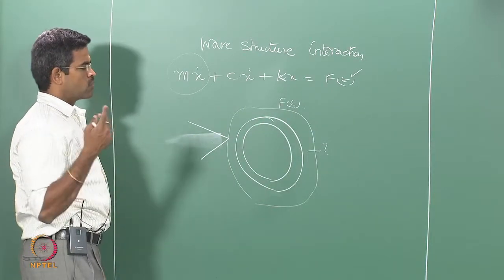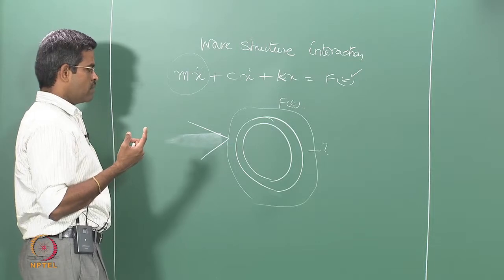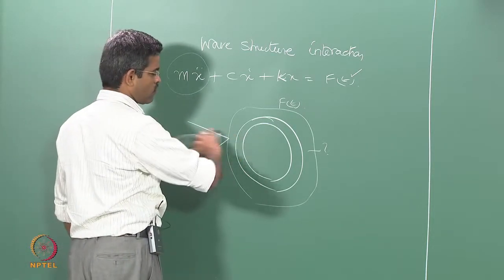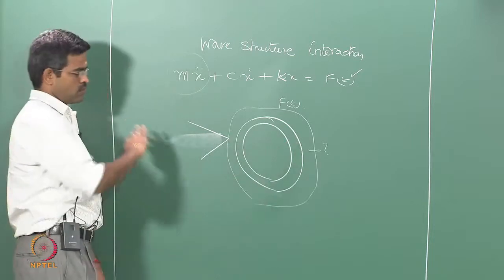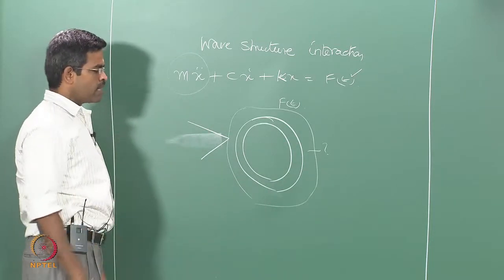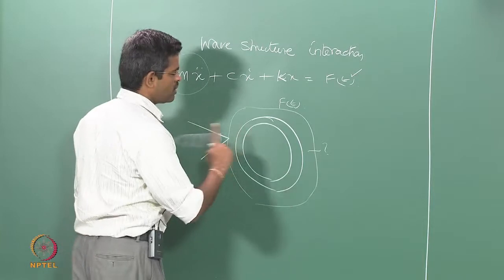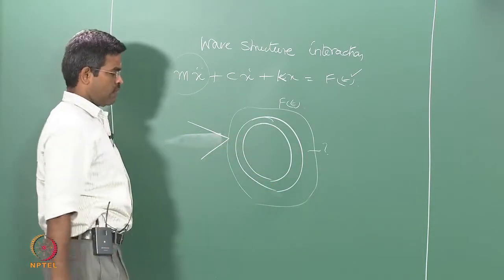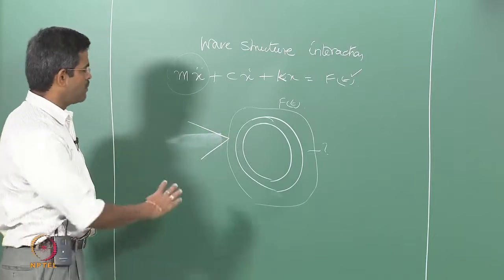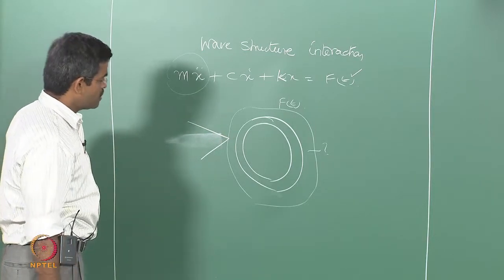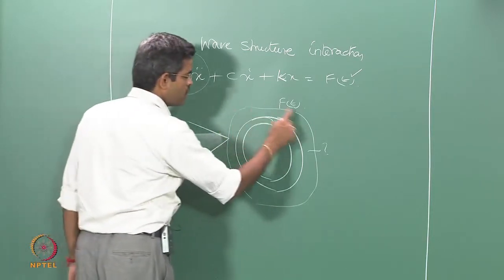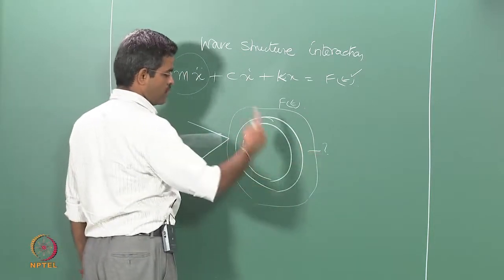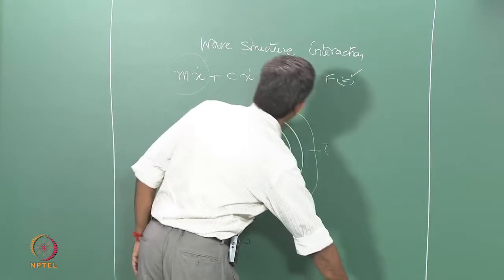So, there are two kinds of forces coming in. One is the vibration induced on the member because of the continuous flow of the water particles, which is called the flow field domain. The second is the secondary vibration or oscillation generated by the system itself, even if it is fixed. Of course, in the case of floating, no question, it will anyway happen. Even if it is fixed, it will have a secondary vibration around its vicinity in both directions, inline flow and transverse flow, which we saw in the last lecture.